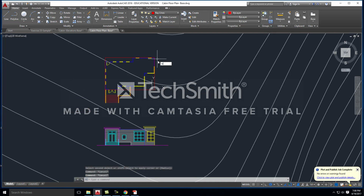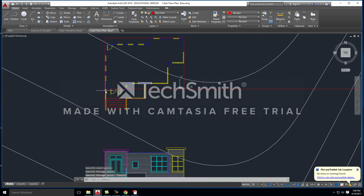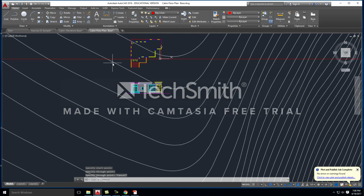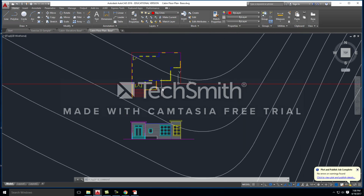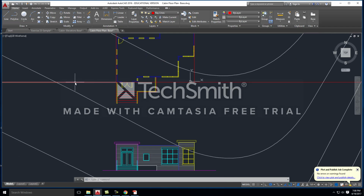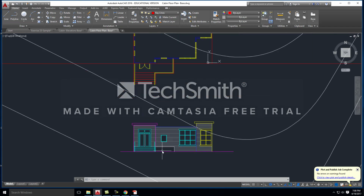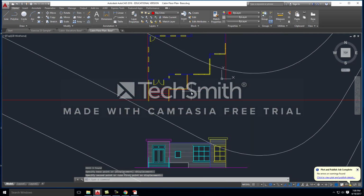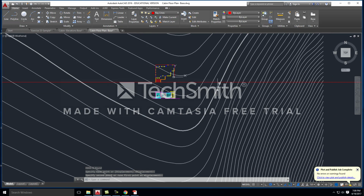Okay, and then from there I'm going to type in ray, and I'm going to make this line extend out like so. This line represents kind of where that portion of the building is cutting at that given point of the topography. We're pretending that our building is cutting through right in front of, in this instance we're actually seeing our stairs, so it'd actually be a little bit further out. So you could take these lines that we've created and move them right to the front of our stairs.